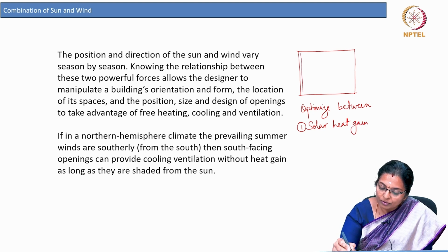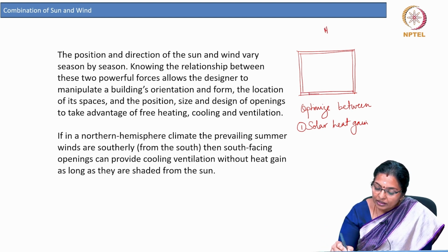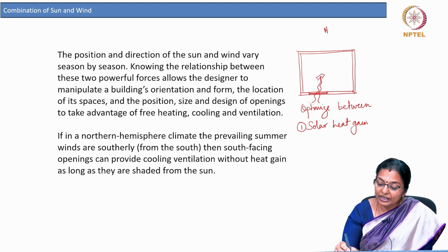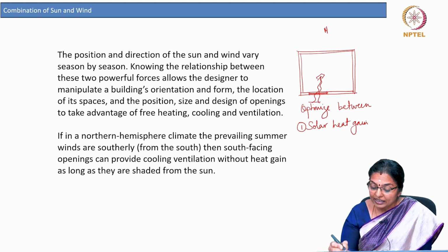So, if you have a room and this is north facing, there will be breeze inside, but you should understand that this breeze can also bring in a lot of heat, and therefore you need to optimize between solar heat gain and the positive impacts of natural ventilation.